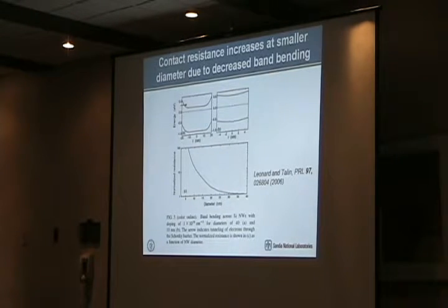Because you have to think, how do we form ohmic contacts? In most cases, we don't actually form an ohmic contact because of band alignment. Unless you're talking about indium arsenide or gallium arsenide, you have a graded junction. In virtually all cases, what we're doing is reacting with one of the components of the semiconductor, for example forming a nitride, like extracting some of the nitrogen.